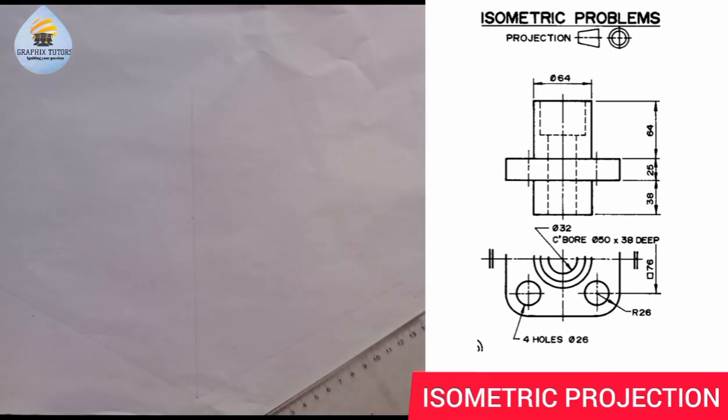And the length here is given to be, you see the square of 76, meaning from the center to the other center is symmetrical. Whenever I see any line like this, it means that what is on the left, what's on the top is also at the bottom, so it's symmetrical. So from this center to the next center is 76, and the radius is 26. So you have 26 in two places. So 26 plus 26 plus 76 will give us 128. So here is 128, here is 128 because of symmetry.